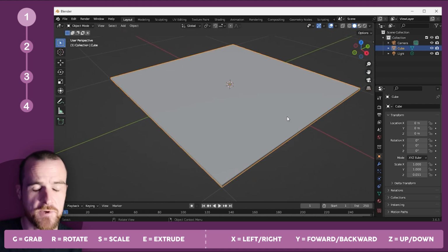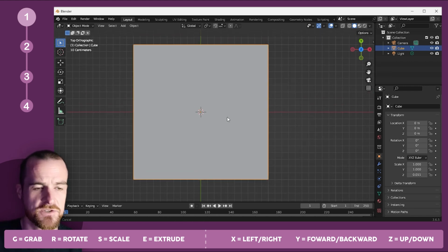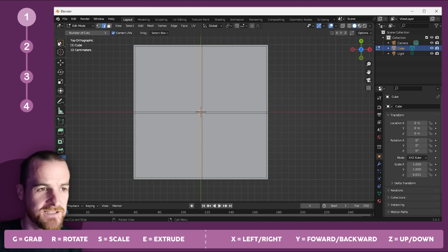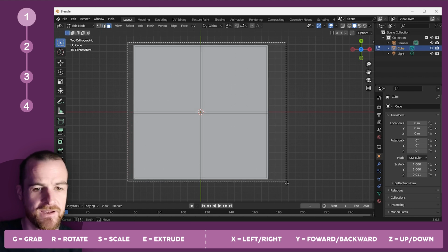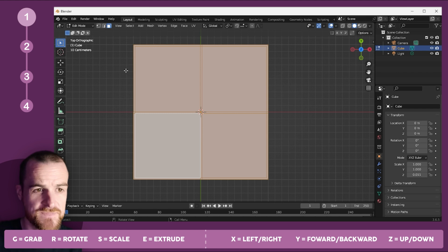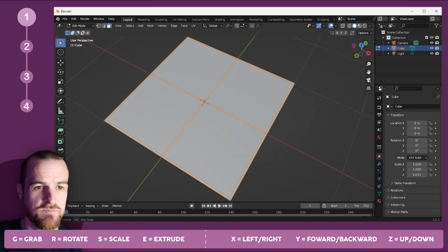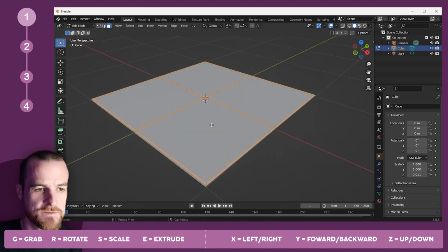Now what we want to do is raise that so that we're creating the walls of our bento box. So I'm going to go back to the Z button, go back to my tab, and select this little face, select the whole thing. So I'm selecting the whole top of the box, and holding Shift, I'm going to deselect the bits that I don't want to turn into walls.